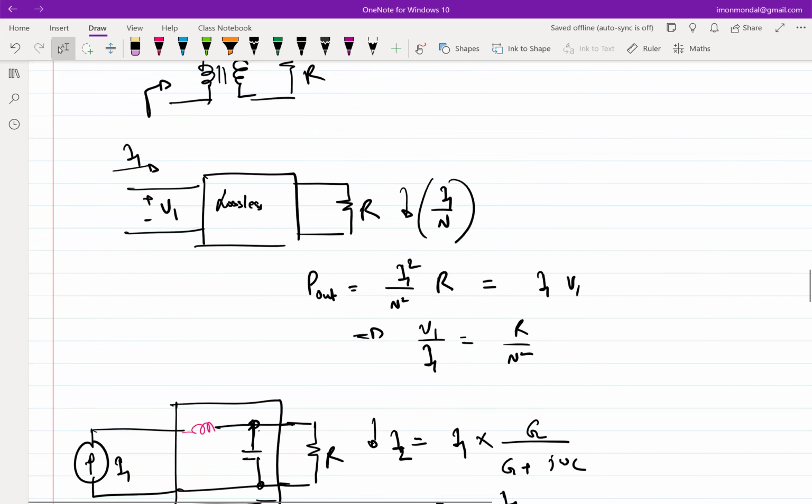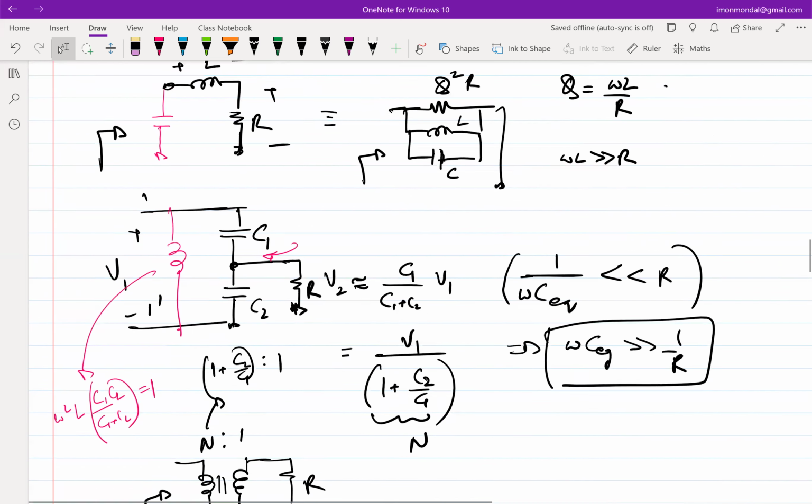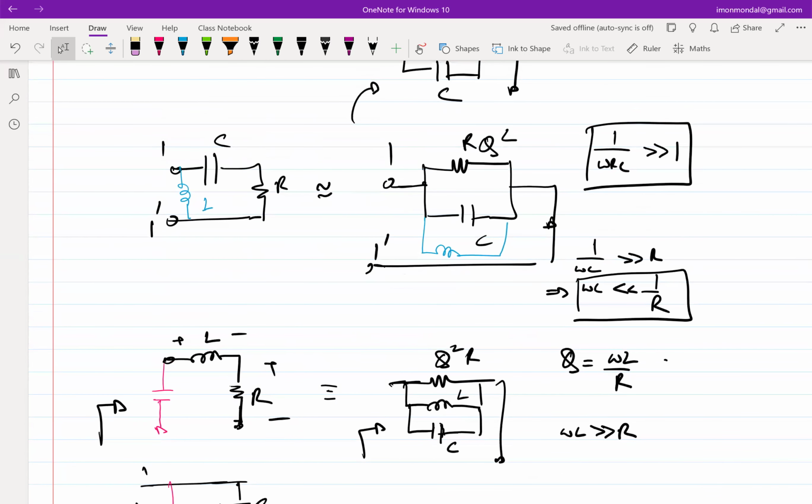Similarly, in this case, if bulk of the voltage is dropping across the inductor, which means the current through the inductor is also large, right? So we'll have more loss if the inductor also has a lossy element associated with it, right? Does that make sense?